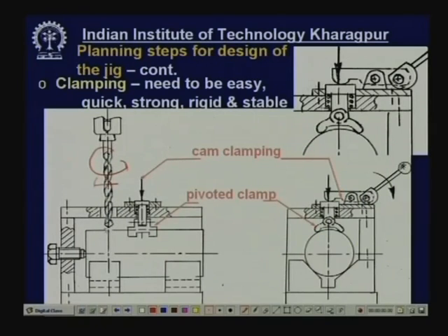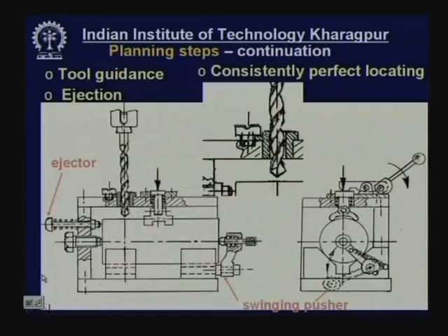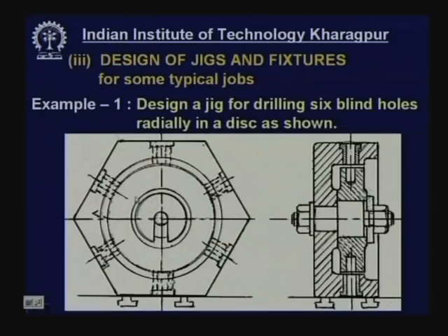Besides that, it has to start on a cylindrical surface, isn't it? The cylindrical surface drilling has to be done. So, the drill has to be guided properly. It should not be allowed to move apart. Considering these aspects, tool guidance is a must, and this will be done by a bush that is shown in the next frame. Here you can see a bush has been fitted here.